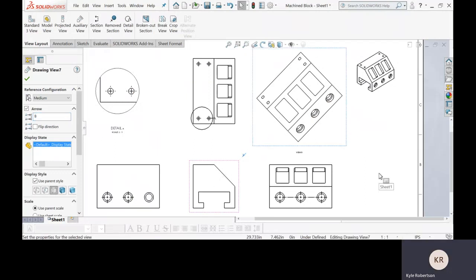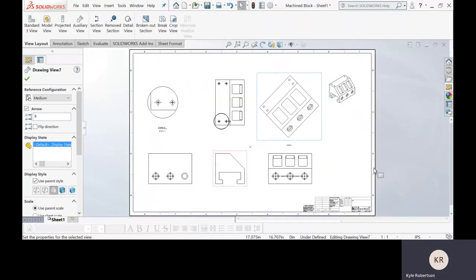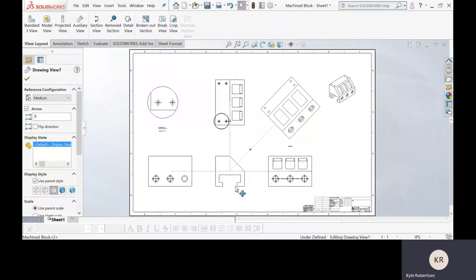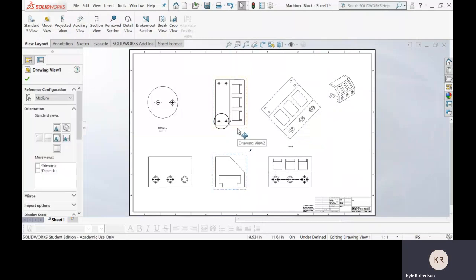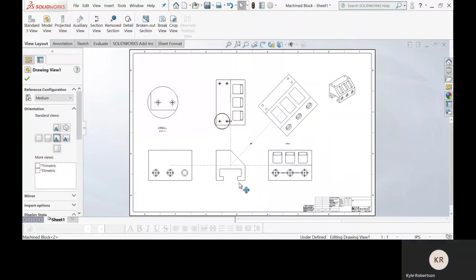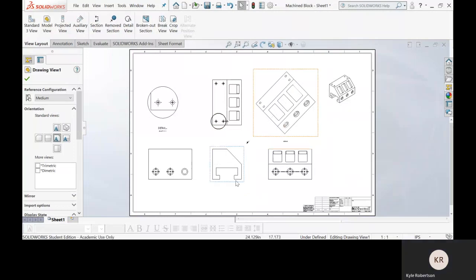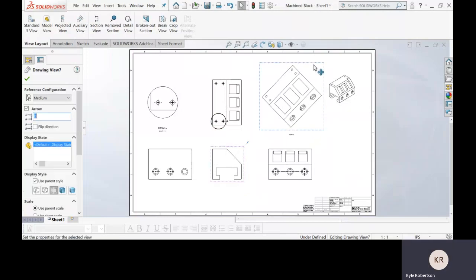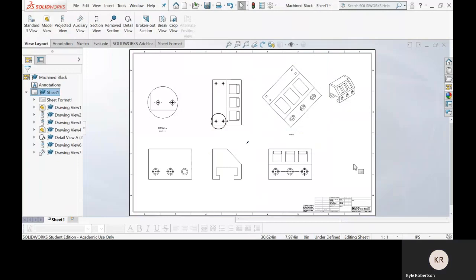We got it placed more or less where they want it. And then you know, read the rest at the bottom there. I just want to show you guys how to use the tools tonight. Page 1615, they're going to show you how to do a section view, okay? So let's keep adjusting things just a little bit here. Let's see, maybe actually move that up a little bit. You can see how everything moves together when we do projected views, so it's kind of nice.